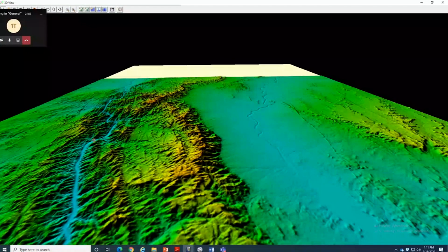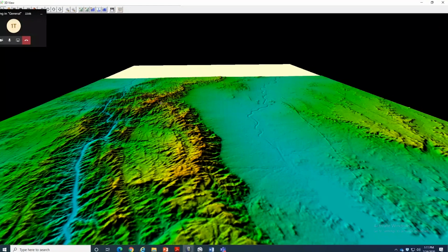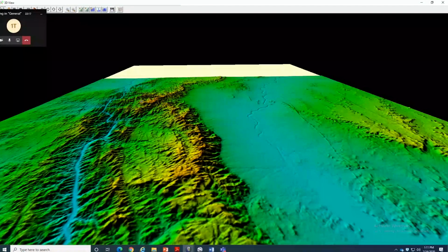Narmada is flowing through the hard rock and Tapi is flowing through the alluvium. The hard rocks are much higher. So small channels will be developing in this area, and at one point of time this upward cutting of the Tapi tributary will reach here. Because of the large height difference between the Narmada channel and the Tapi channel, the flow of water from some tributary may be taken towards the Tapi. This process we call river capturing.